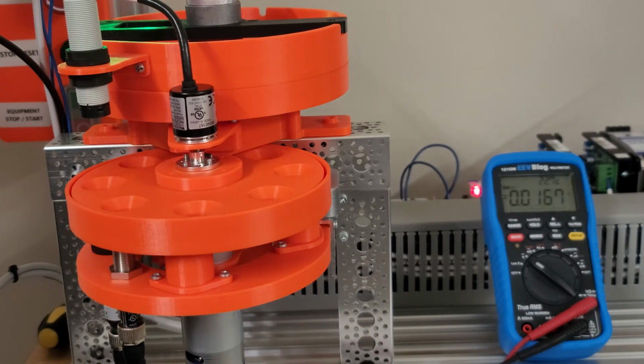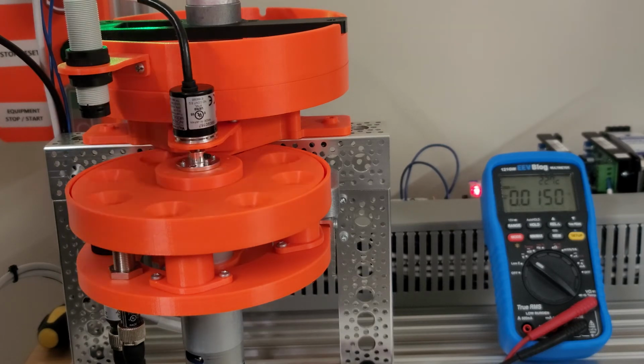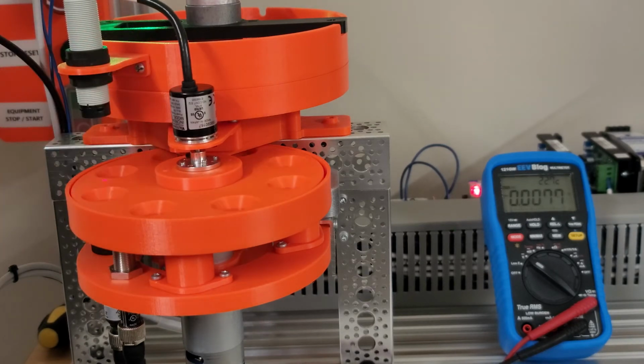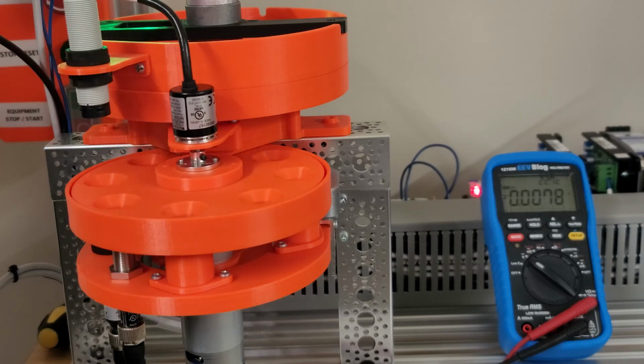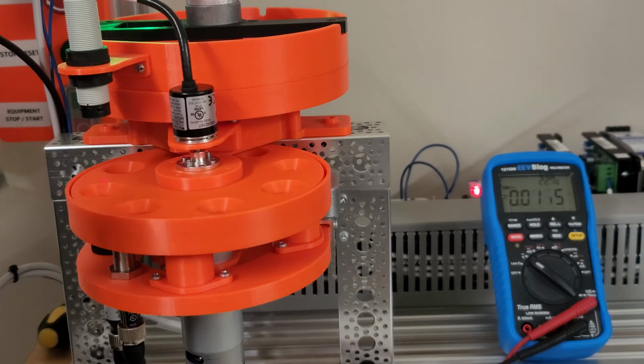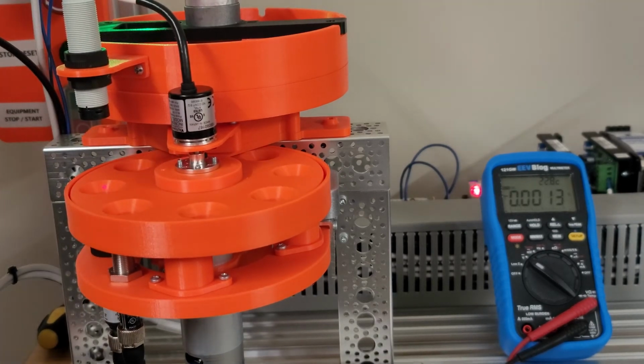But that is also something else I haven't really tested, which is validating that when I command 12 volts, for one, is it getting 12 volts? And for two, is that 12 volts equaling out to the relative RPM, plus or minus a certain amount of tolerance, to what I expect to see? There's a few things that we can take a look at.